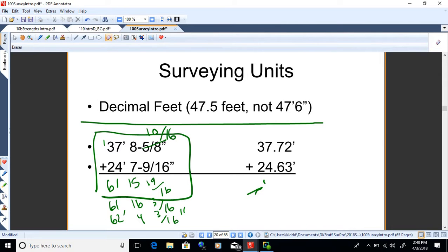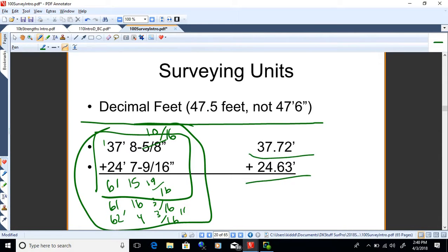It's kind of dumb, really. You can see why people like the metric system better. And see, so a surveyor would not measure the distances like that, because it's dumb, okay? What they do, they use decimal feet. It's like a metric foot, essentially. You take a foot and you break it up into hundredths. And these are the same two distances that have been converted to decimal feet, and, you know, I can do this pretty easy. 62.35 feet, and I'm done, okay? So that's how that works.